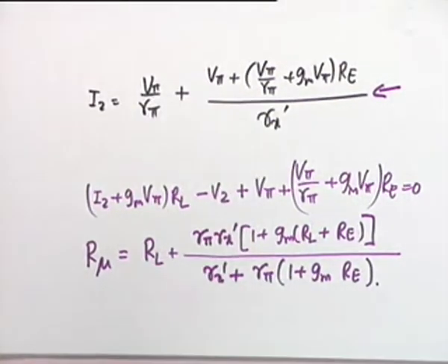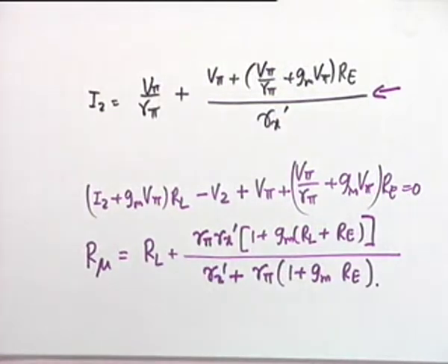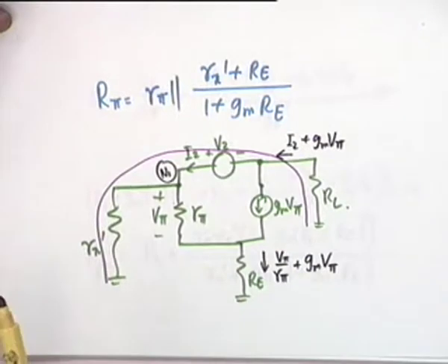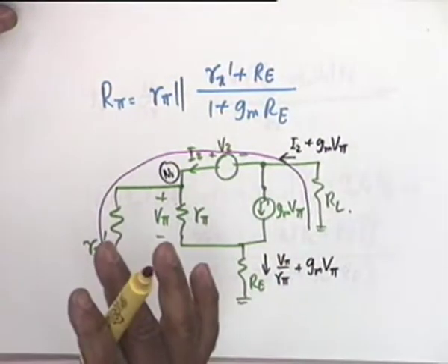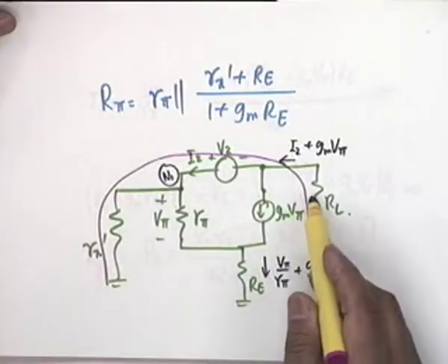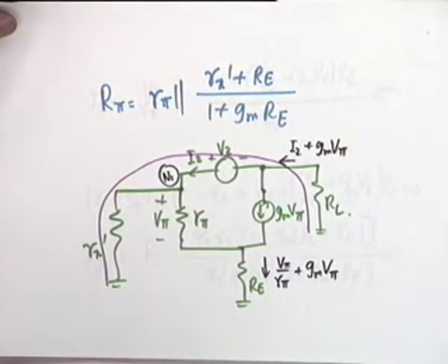One wonders, after obtaining this expression, that RL comes in series. Now in the original circuit we could not identify that. You see, V2 and I2, if RL had come in series, we could as well have omitted it and then added it later, just as we identified a parallel component and we said we will throw this out, we will calculate the rest of it, then parallel it. We could have done that here also. We could have shorted RL.